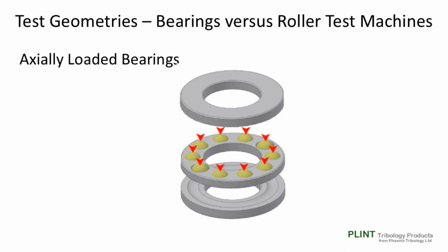If a test is to be based on a standard bearing, it makes sense to choose bearings with an even number of rolling elements. For example, a 7209 angular contact ball bearing usually has 12 balls. This means that this bearing can either be used for tests with the full complement of balls or with the number of balls reduced to, say, 6, 4, or 3 evenly spaced balls.